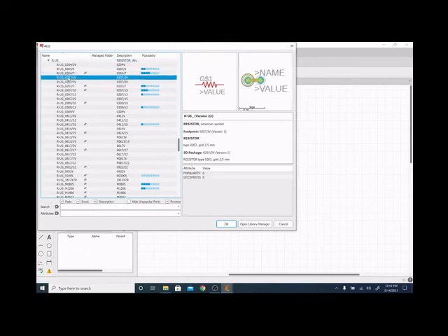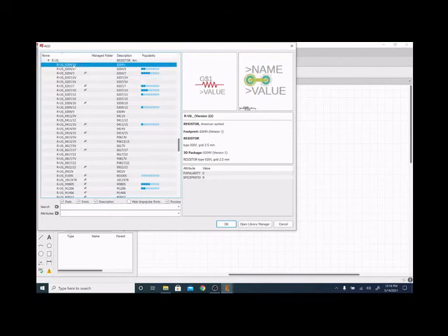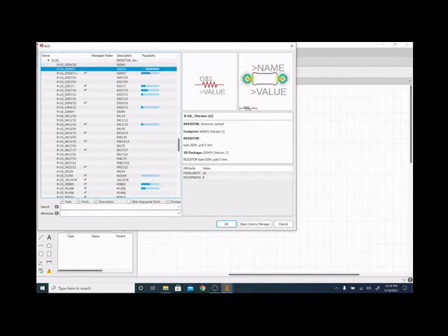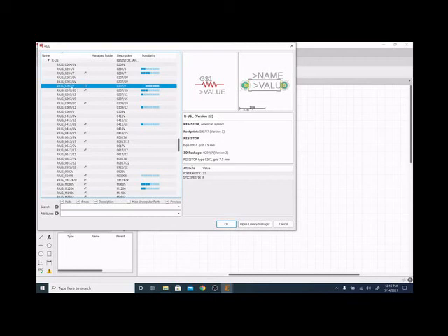And I can either go for the compact, what these numbers refer to, I guess I should explain that. So you have the 0204, which stands for the diameter and the length of it. And then the V stands for vertical, so if there's no V, then it's horizontal. I find the ones that fit the best for me are the 0207 or the 0207/2V, which is a vertical package for the same one. So go ahead and pick whichever one you're going to use.